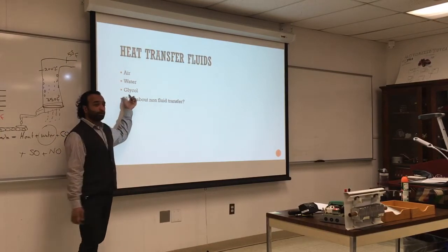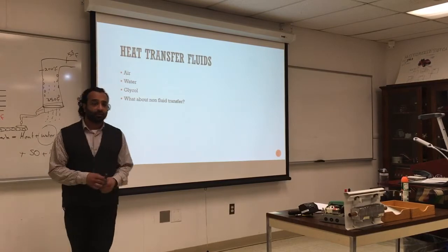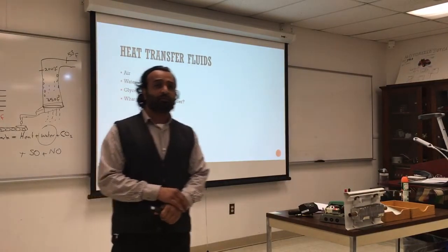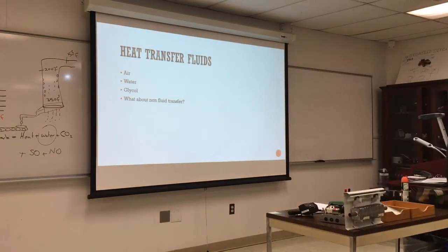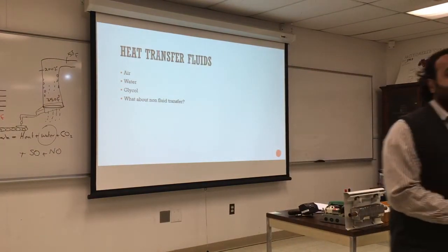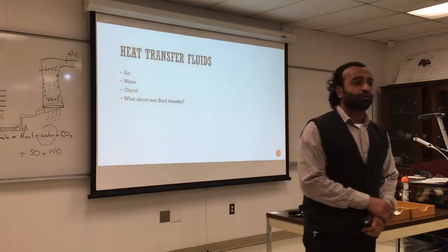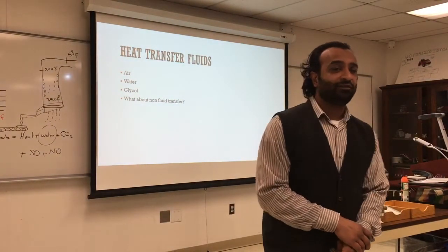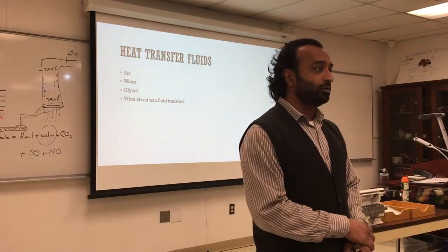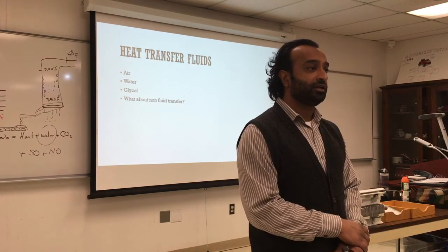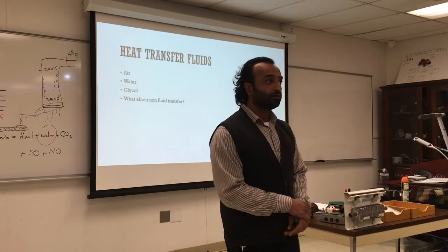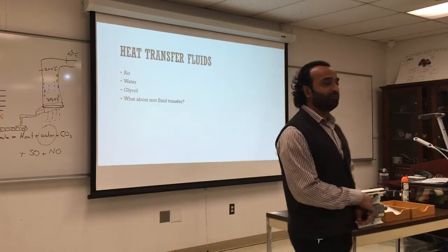We can use black oil or antifreeze. That's very important when you are in places where the temperature drops quickly. If you put only water, it will freeze. And to make things a little bit more analytical, you can look at your car system. If you live in New England, you cannot just put regular water in your radiator. It will freeze and it will break your engine and your radiator. So think of the car heating system, which is very similar to what you have in your house.